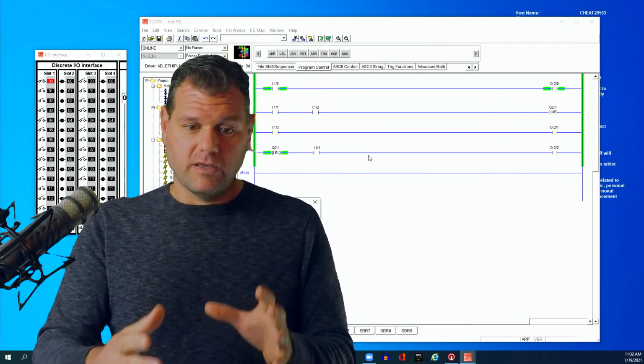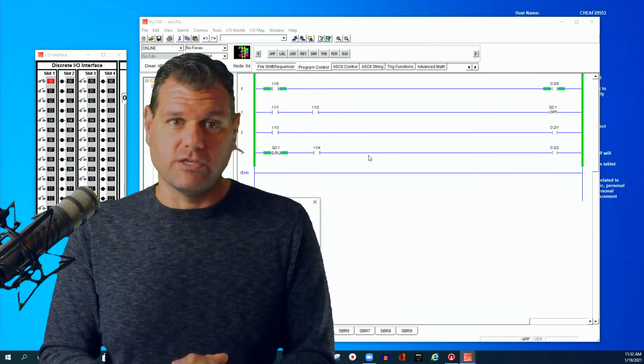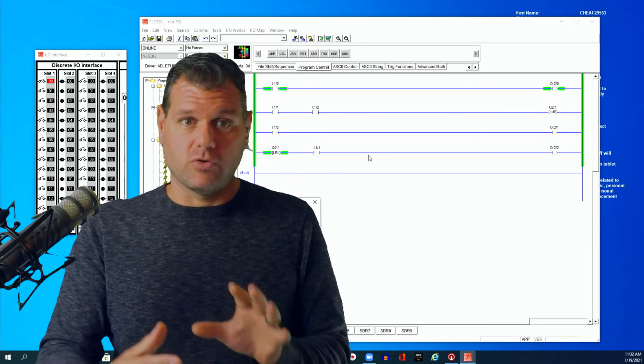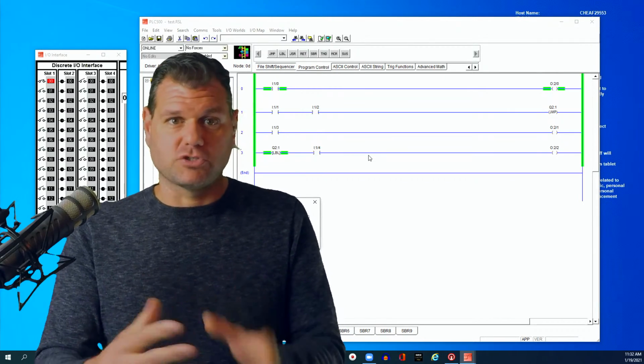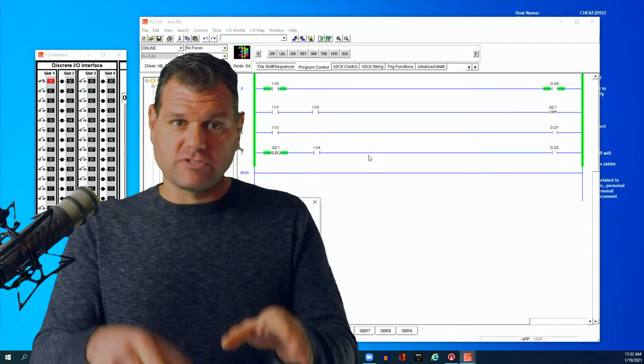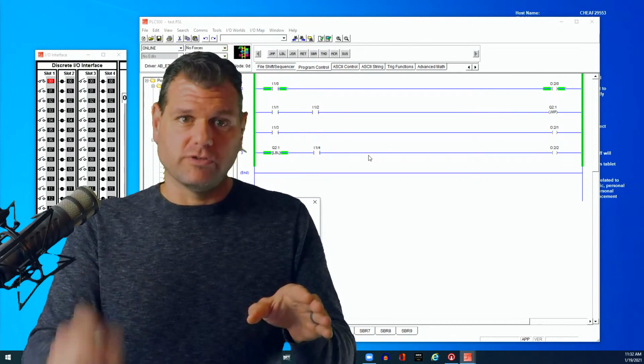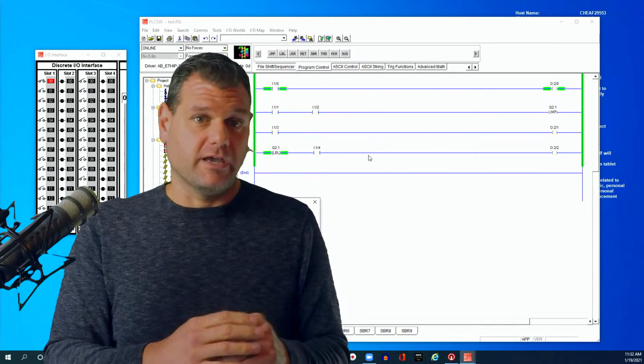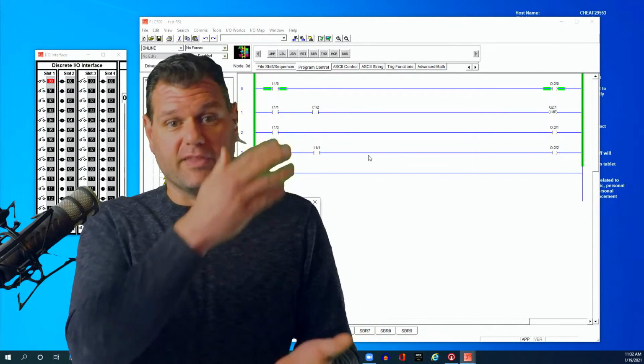And then, for whatever condition, let's say that you don't need to look at that code. Let's say you don't want to access or turn something on. You can jump right over that, and that's fine. If for some reason you needed to double back, you could tell it to jump back to, let's say, rung 19, and then you can have it scan again.